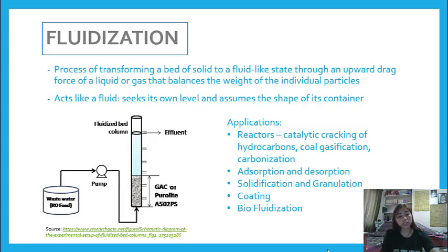So, in the figure below, it is an ion exchange operation, which actually involves the fluidization operation since it has a fluidized bed column. In here, our fluid is the wastewater. It is pumped to the purolite. Our purolite is our solid. Then in here, adsorption occurs in the purolite. So the purolite absorbs the calcium and magnesium. And after our fluid has passed through the purolite, our effluent will now become clean.